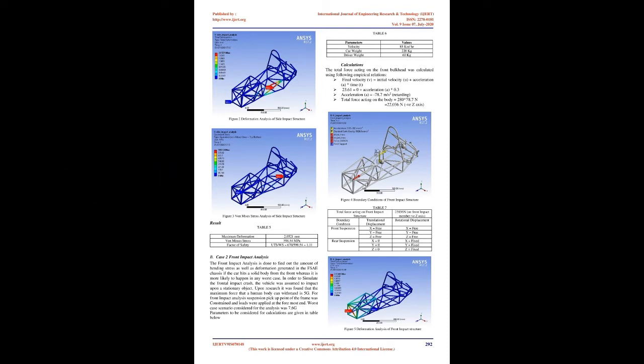For analysis, 4 types of analysis are performed on the FSAE chassis. The chassis undergoes bending due to the weight of mounted components on the vehicle like the engine, fuel tank, dampers, etc. In the dynamic events in FSAE, the chassis is evaluated for acceleration and cornering ability, which leads to twist in the chassis, and this can be judged with the help of torsional analysis.